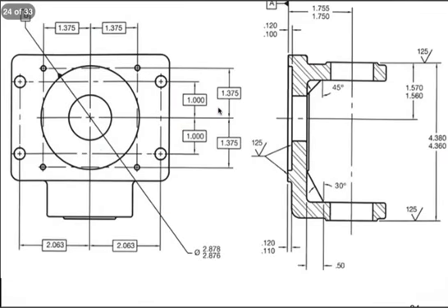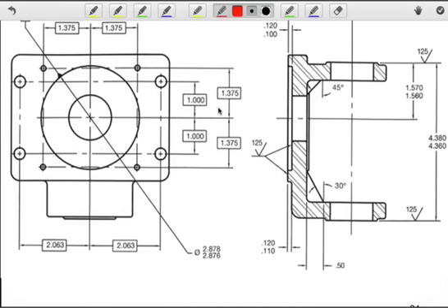Okay, so here's an example of what you might see on the design spec. How do we know that we have surface texture? And of course, we're concerned about that primarily because this will be a costly operation. It's going to add significant cost to our part. And it will also increase our lead time to produce this part, as we'll see later on. So we're looking for our checks indicating that there's a surface texture specification.